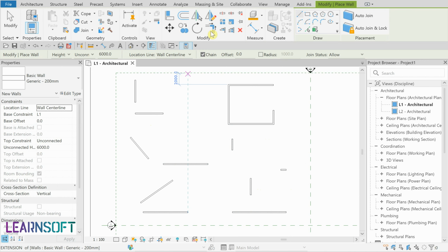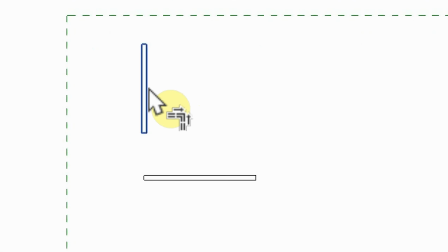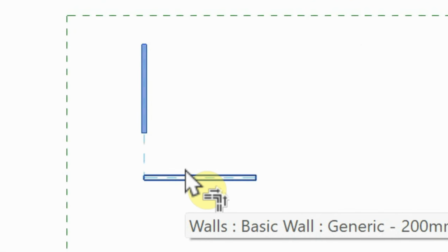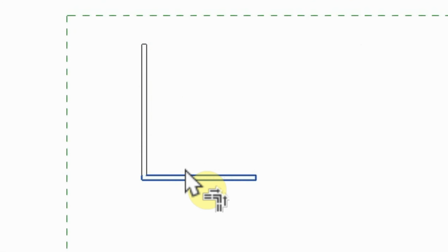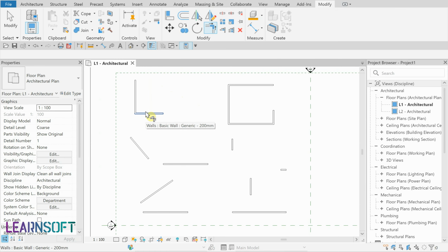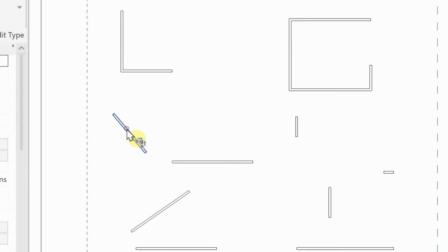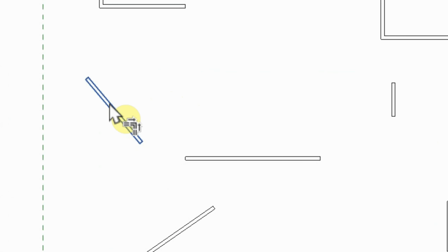Select the Trim tool and edit shapes one by one. Here we want to extend elements to create a corner. Click one by one. Click on the two sides that you want to keep. When selecting an element that needs to be trimmed to form the corner, make sure you click the part of the element to be retained.